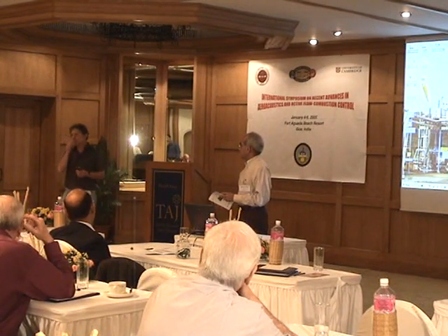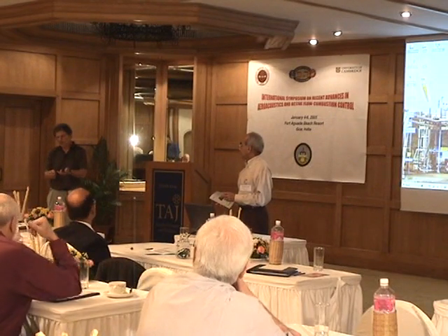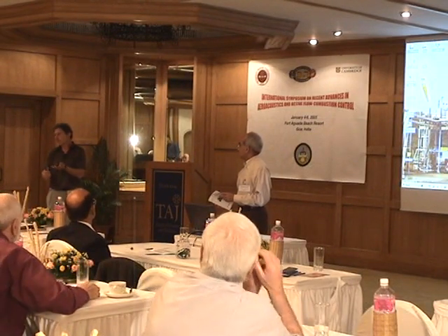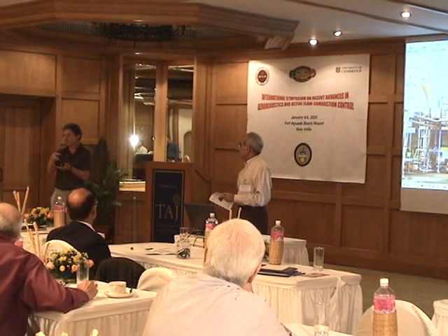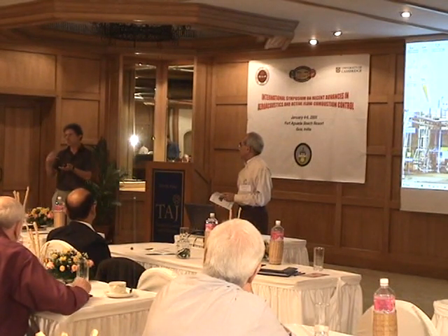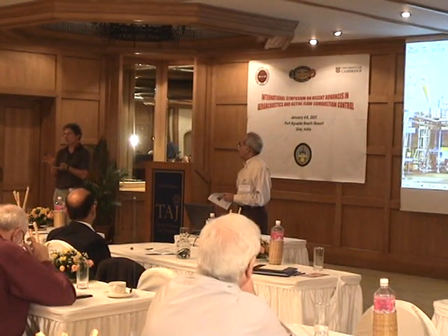But with HHC, you are limited in frequency. For instance, if you act with a 4 per rev in the fixed frame, this translates into 3 per rev or 5 per rev in the rotating frame. So you are limited in frequency in the rotating frame.